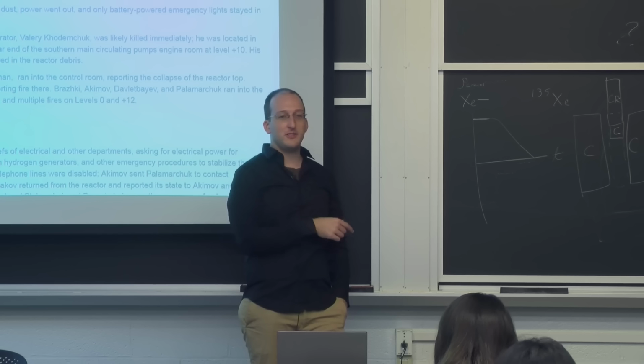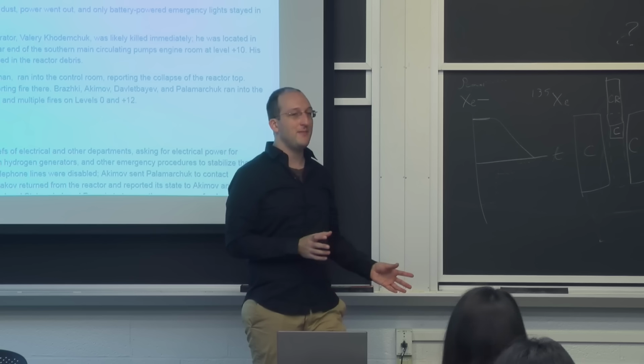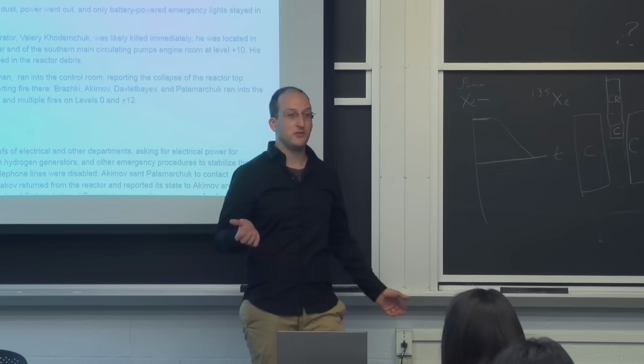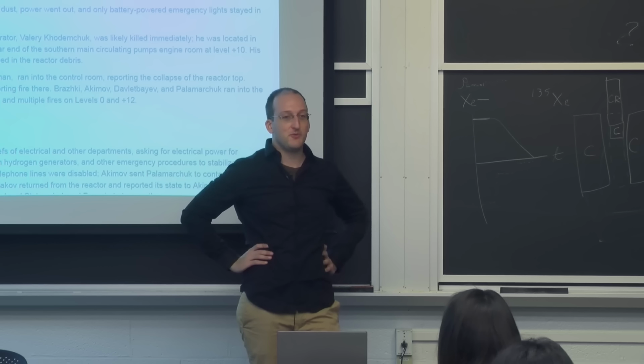We had to drill a hole in the side of the wall so that the hydrogen would vent outside, and do some calculations to show that if the entire bottle of hydrogen emptied into the lab at once, which it could do if the cap of the bottle breaks off, it would not reach 4% concentration. So hydrogen explosions are pretty powerful things.